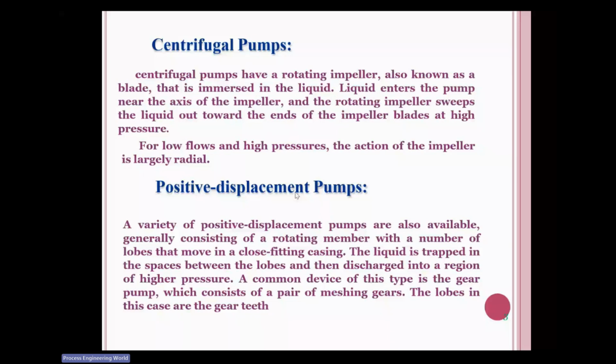Okay, anybody else? It will increase in centrifugal also. Yes, yes, you can tell. In a positive displacement pump, the pressure increases tremendously, very much. So we require a PSV on the outlet because in the performance curve of a positive displacement pump, it is a vertical line between head versus flow rate. Right.